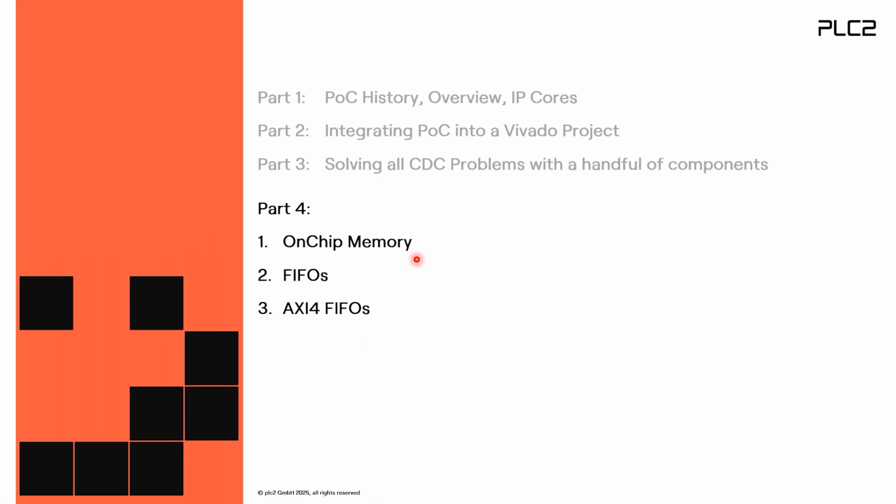I have shown you, starting with the on-chip memory abstraction layer, a vendor independent, device family independent implementation using generic VHDL code, and in certain places vendor specific code where the PoC-Library can switch between implementations.